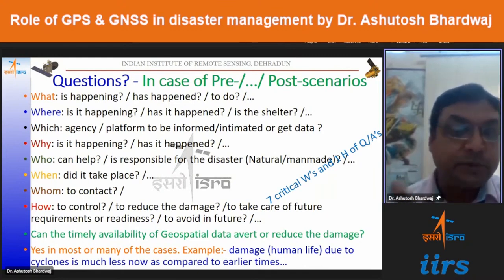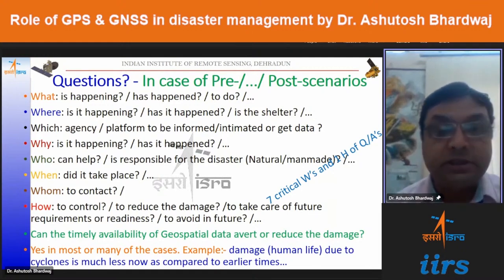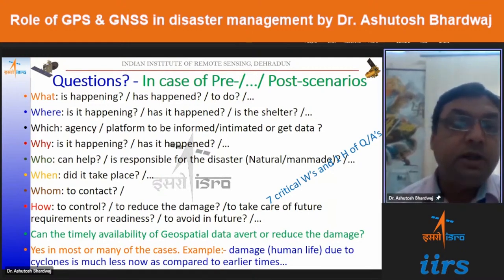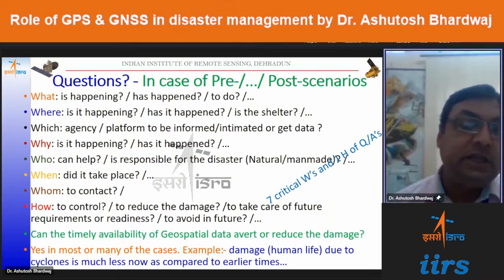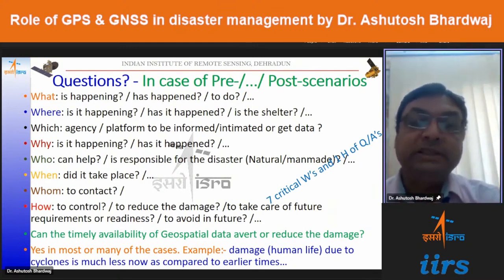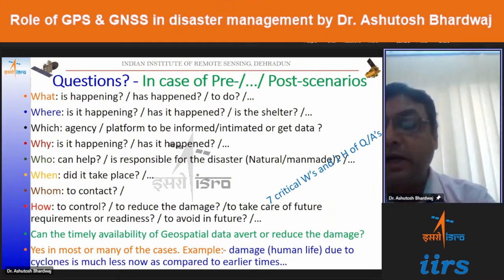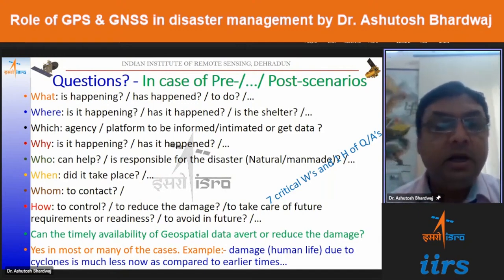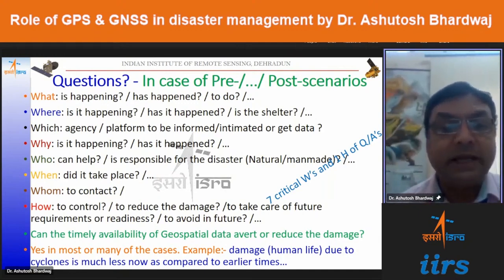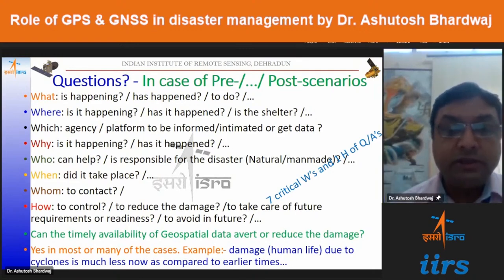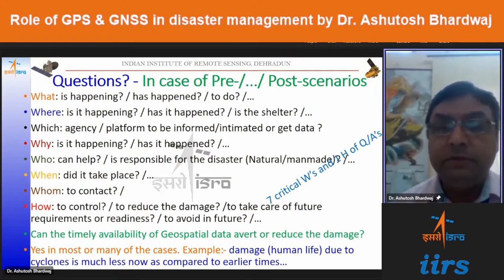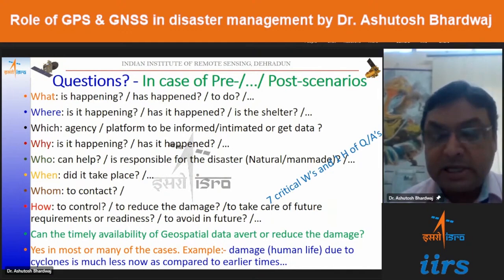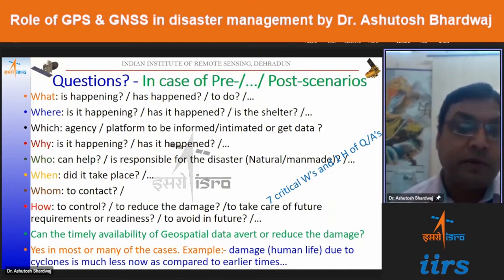That means basically we have the exposure orientation coordinates, which provide us the position of the exposure station in terms of the XYZ. And besides that, we also know the sensor attitude, that is the omega, phi and kappa. That provides the rotation of the sensors about the XYZ axes. So that is called the onboard triangulation. So GPS is always there somewhere in the background.